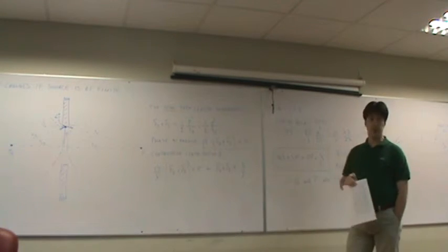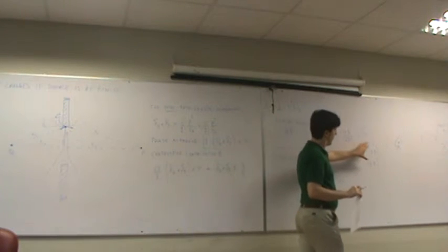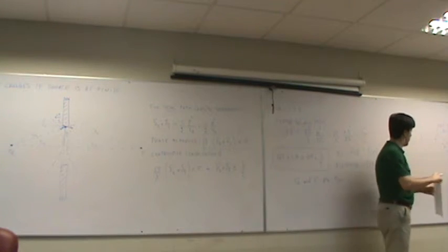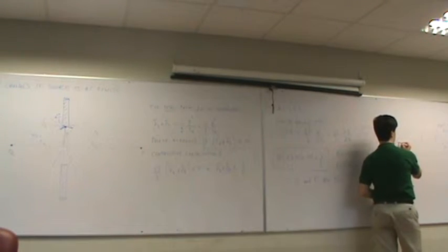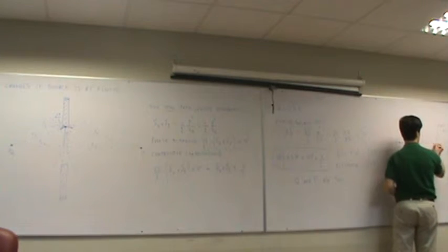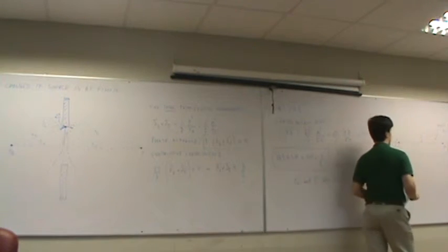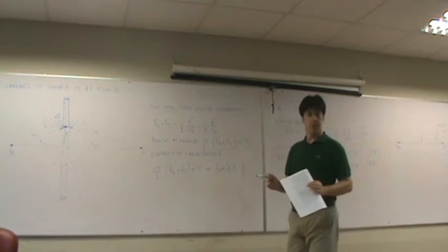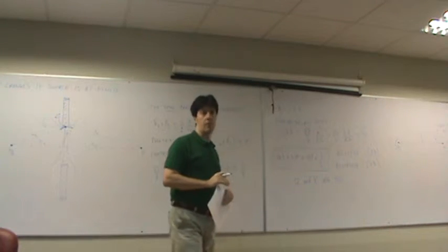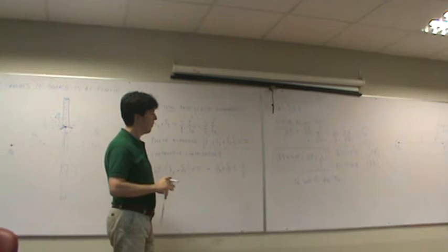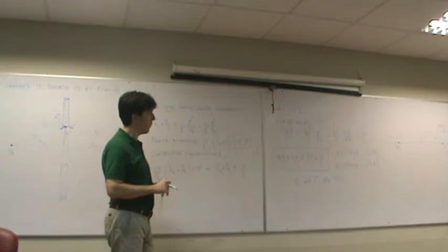And when you design a radio system, the recommendation is to keep the first Fresnel ellipsoid, that is all this volume around the radio link, because the radio link is from point Q to point P, free from obstacles, if possible. We will do some practical applications of this.